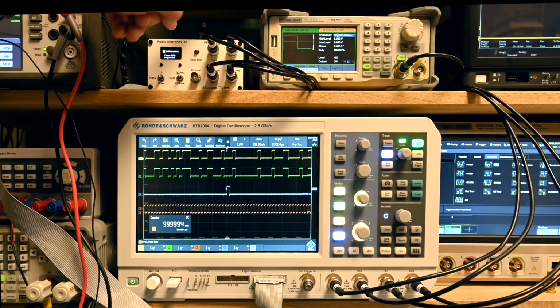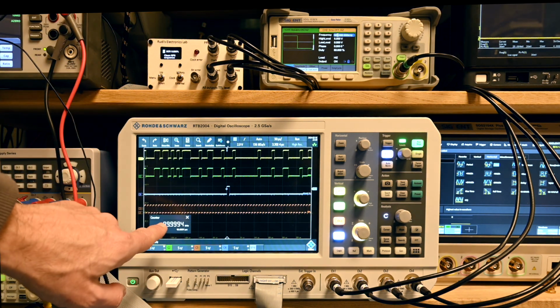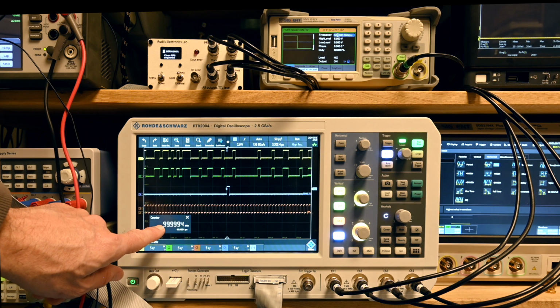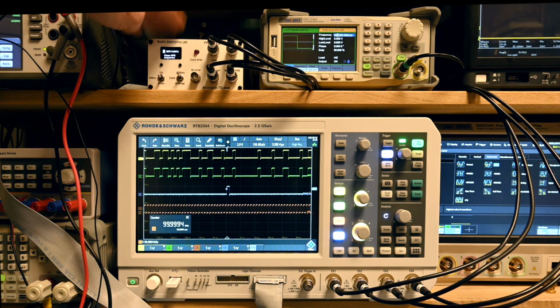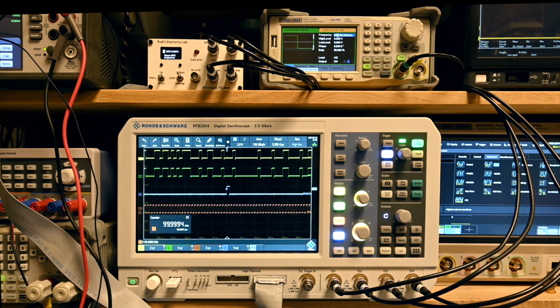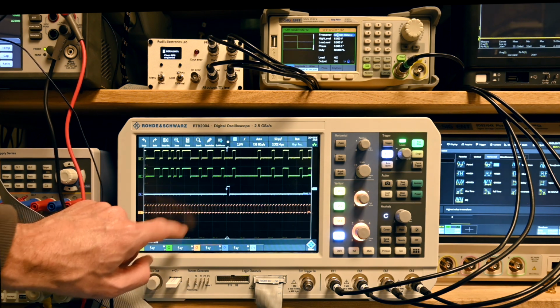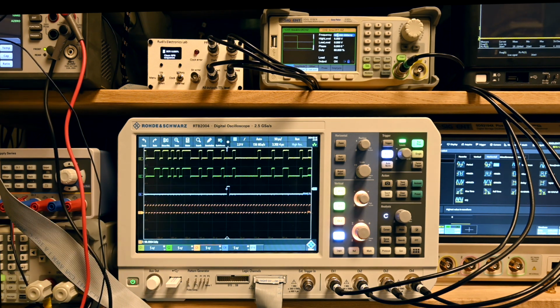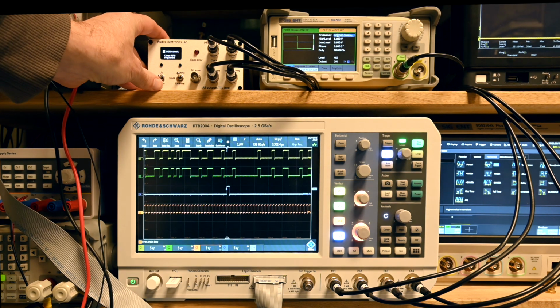And finally on the clock output, which is right over here on the device, we see the clock, and the clock right now is about 100 kilohertz, and that is the built-in clock from the crystal in the device. It's a 1 megahertz crystal divided by 10. So that's more or less what we would be expecting here. I'm just getting this out of the way here, and we'll have the clock signal also down here at the bottom. Now, the basic purpose is that we can introduce some errors into the signal.